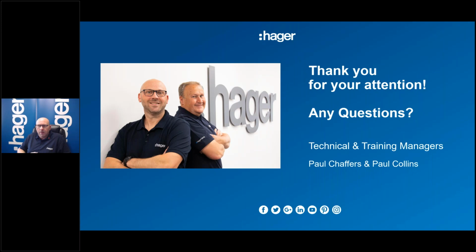Cheers. And last but not least, from Stephen, can you still use plastic consumer units outdoors? Yeah, we're starting to see that actually, especially with EV charging, we're seeing different approaches to people getting that power to the charger, and there's nothing wrong with a plastic consumer unit used outside. So the regulation, off the top of my head, is 421.1.201.